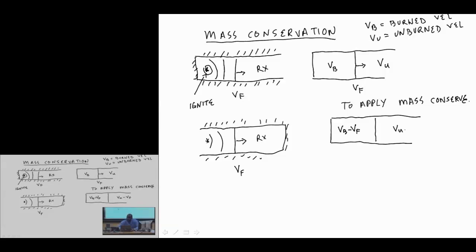And I'm still going to play this game, and you're going to say, that's kind of crazy. I'm going to say, hey, look, these are just flows, so I don't really care. I subtracted this off. I know the mass is conserved, so from my perspective, all I know now from a mass conservation perspective is that the density over here times the velocity of the stuff here had better be equal to the density on the right-hand side times the velocity on the right-hand side, okay?